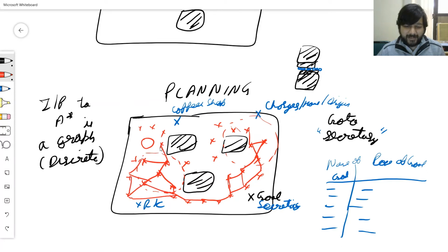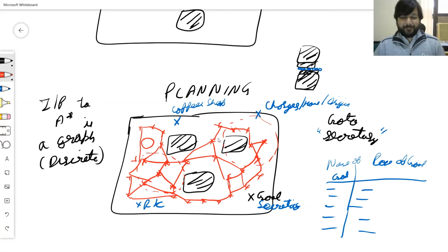Because what you do next is that after joining all this up, this is offline. So we do this when we get the robot. So the first thing that we do is always a SLAM. The second thing that we do always is make this offline roadmap. It's exactly the same as Google Maps. So of course they use satellite imagery to make a map, but those are heavy algorithms that extract roads from satellite imagery. So they've done that offline and they've converted it to graphs offline. So we had a continuous space, we've converted it into a graph offline. Then we also temporarily add the source and the goal to this roadmap.